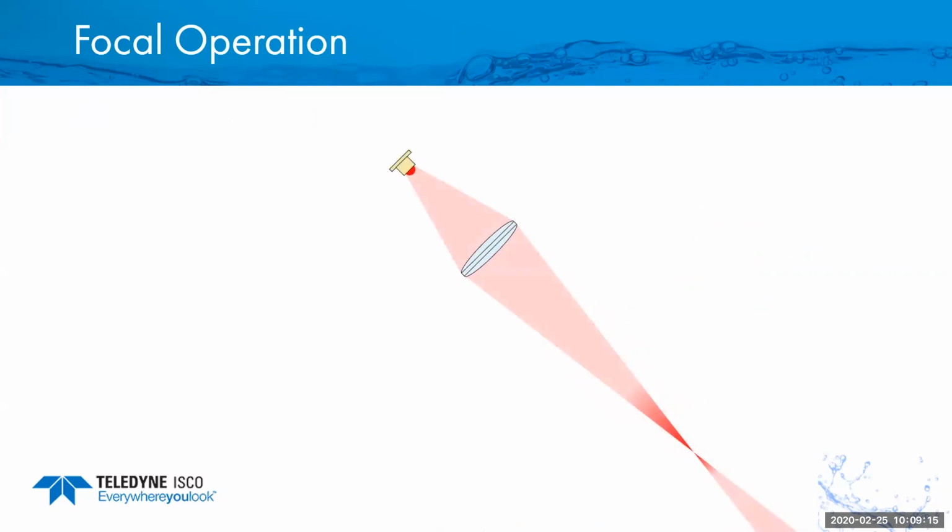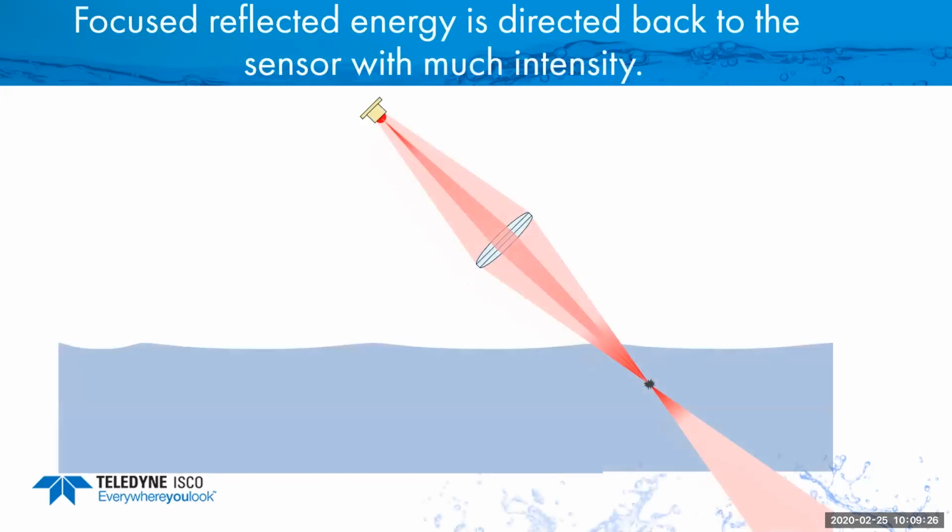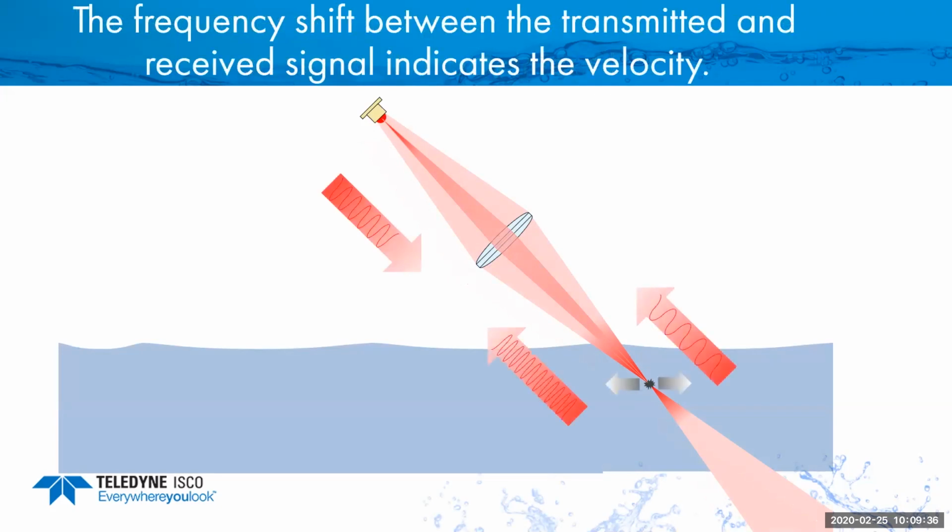But now let's talk about the laser and what we do with that. A laser pointer has a constant focal point, so a laser pointer will just shine on pretty much to infinity. But anyway, the focal point is the key part with the laser. We actually know where the water is, and what we'll do is move the laser and focus it below the surface. So we change where the laser is, we know where the water is, and we know where we want to focus. Like any Doppler device, we know the frequency we're transmitting, and we know the return frequency, to calculate the Doppler shift.